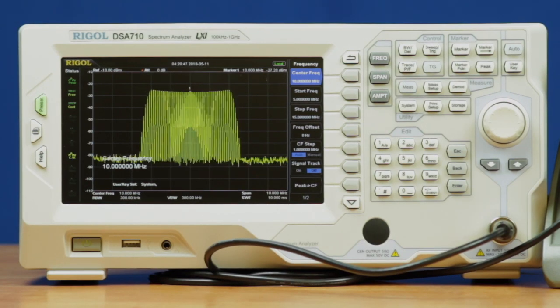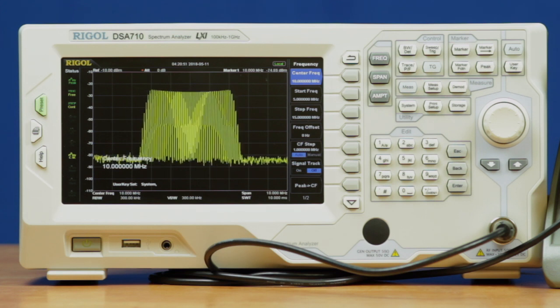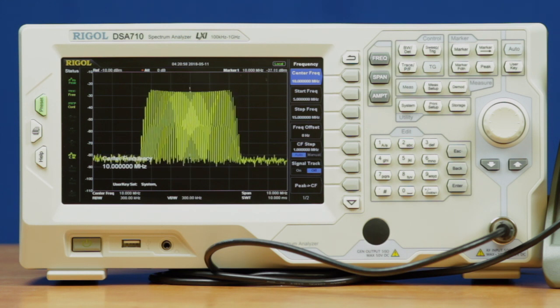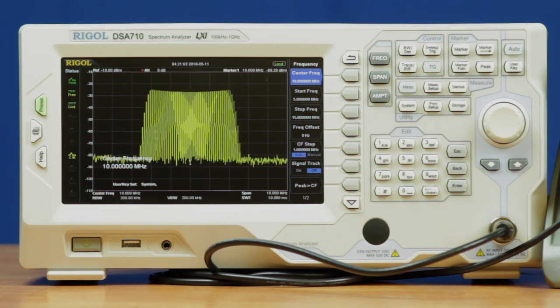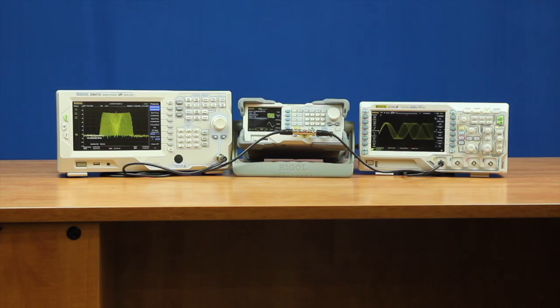We see the same thing illustrated on the spectrum analyzer on the left. Here we can see how the frequency is quickly moving, about half the screen width, from about 8 megahertz to 10 megahertz. Actually 8 to 12 megahertz, centered around that 10 megahertz in the middle. So that's giving you that frequency shape that's shifting quickly, modulating between different levels, and that's how you can encode analog data, just like an FM radio station, selecting different frequencies for different data bins in each area. So that's FM modulation.